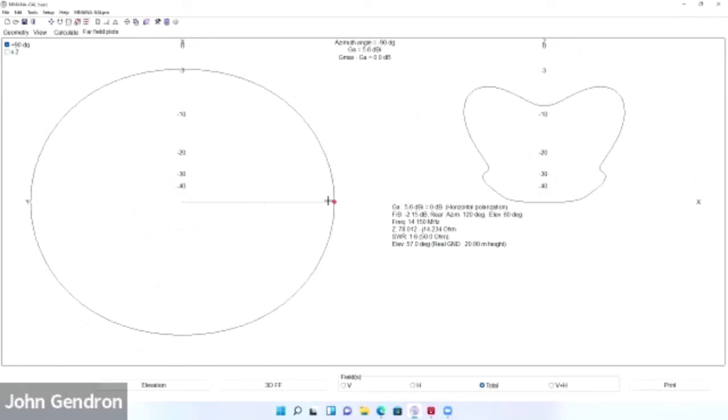I could just go to this menu in here and fill out all those pieces. So you're just testing it. This is going to give you an approximation of what the antenna will perform like. Now, keep in mind, this is a model. With any kind of model, whether it's a health model, an electrical model, an antenna model, a climate model, it's only as good as the information you put into it. So if your ground setup is wrong, or different than what you put in here, or you put the wrong material in, or you build it out of something else, all bets are off.